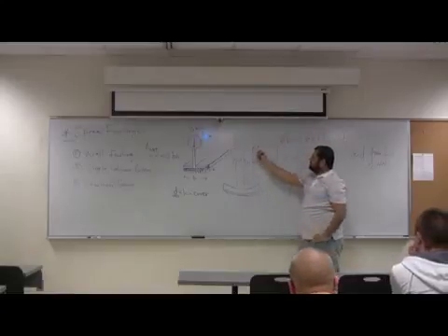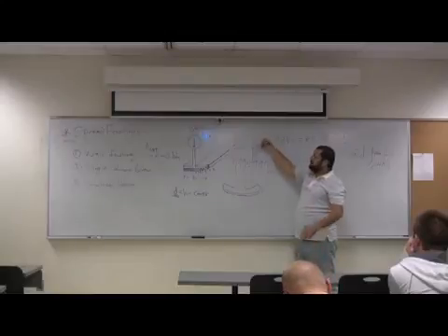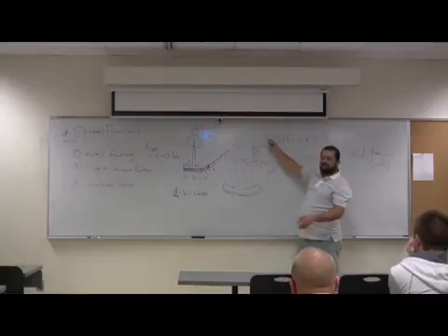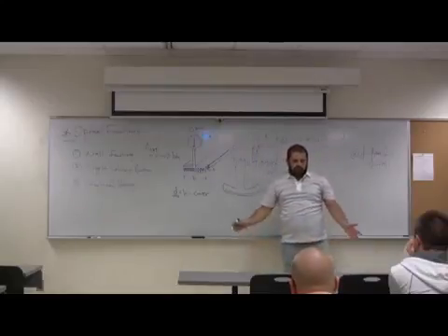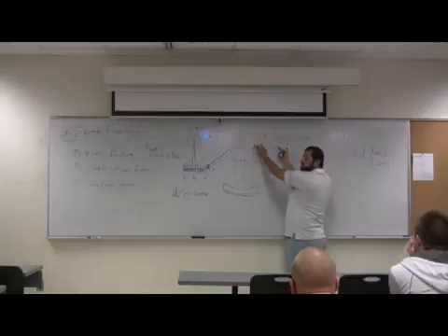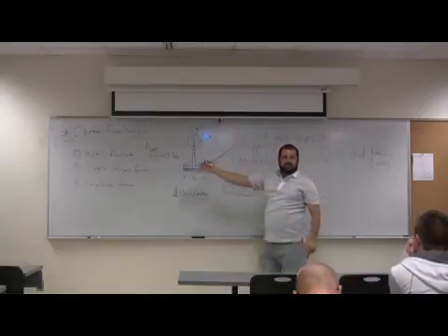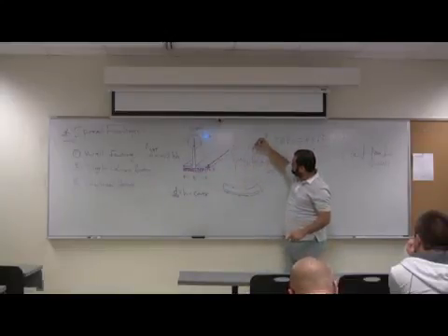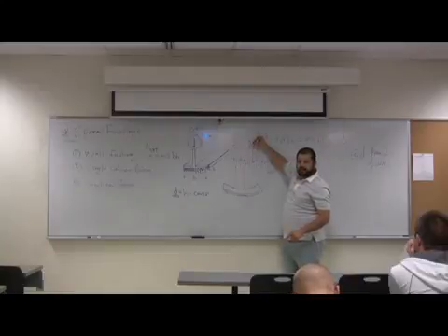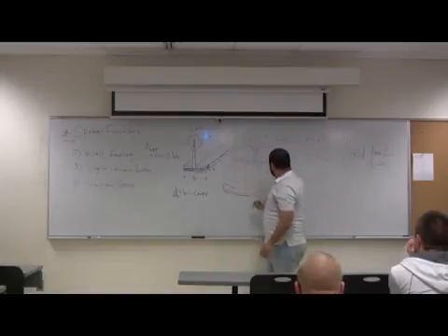So the maximum moment here, if this is w, and if this length is whatever, call it L, for a cantilever is wL squared over 2. So w times this length squared over 2. That's the maximum moment you use to design for flexure. For shear, what is the critical section? At d from this, which is basically this section.